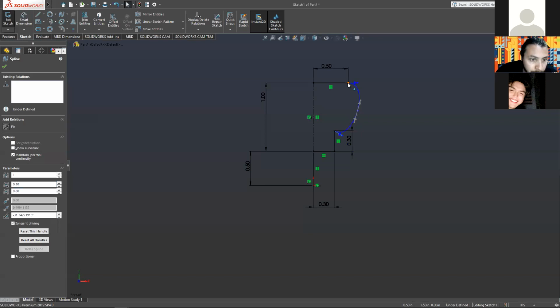Okay, so tangent driving here. What were the parameters for it? We just changed the angle to 0, and if it inverts itself, change it to 180. Ooh, I can't select that angle. The little arrow. Yeah, the box is not letting me. Give me a second. Make sure you have that tangent driving. Like you can't click the arrow itself.